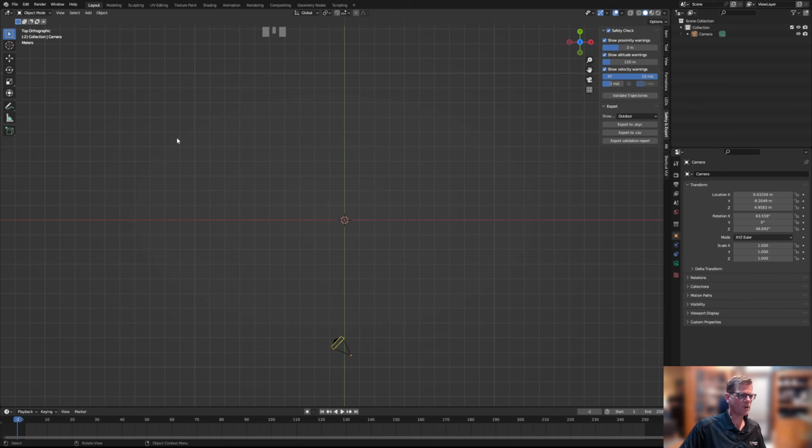And while I'm here, there's a few other add-ons I want to point out that I find to be helpful. One is the extra objects add-ons, the add curve and the add mesh. I think I'll show you both of those in the tutorial. Another one is called loop tools. The mesh loop tools are helpful for getting vertices spaced evenly. And then another one, which I don't think I'll have time for in this tutorial, is called Animall, and that helps you to animate the individual vertices within an object.